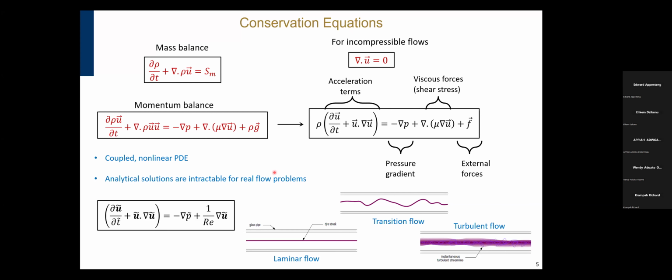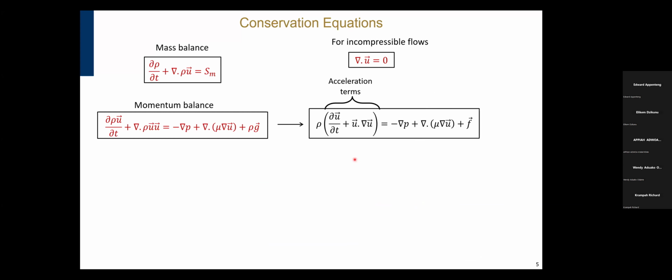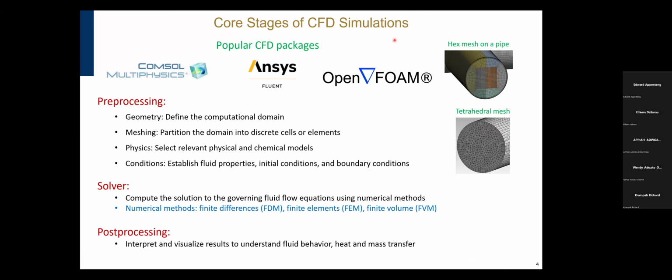Okay, so there is another question. What are some considerations when choosing a mesh? So in the past, if you had an unstructured grid, for instance, you would most likely have issues with the solution because tet meshes are relatively bad.